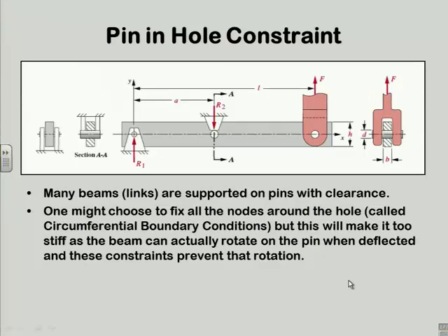Now, I think one's first instinct would be, since I have a pin and a hole, in my analytical model, I pretend there's a force at the center of the pin, right? And the pin somehow distributes that around the hole. There's really line contact, but then there's some deflection, and I get a little bit of a contact patch, right? And I don't even know or care in the analytical solution what that business is, because theoretically I have a point load or support at the center of the pin, right? Unless I'm interested in the stresses between the pin and the hole, I don't care about any more than that.